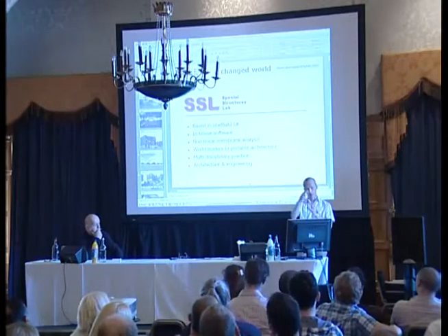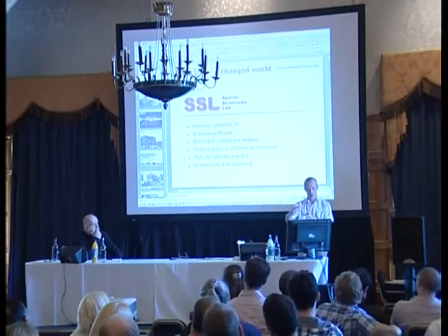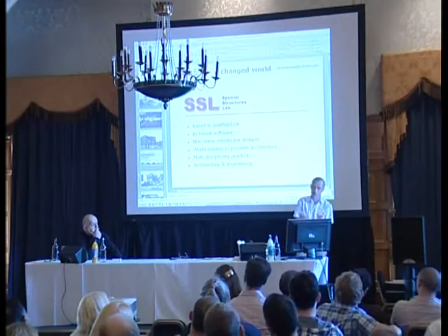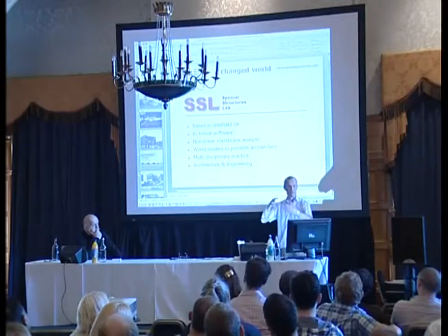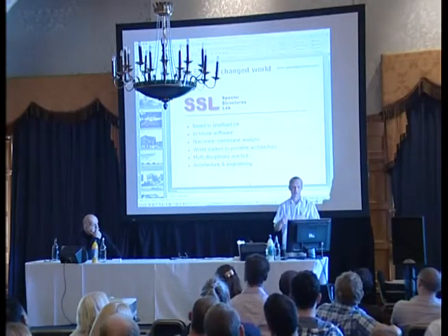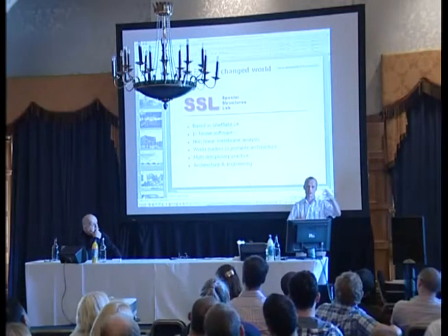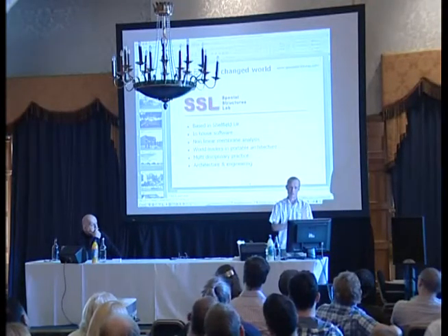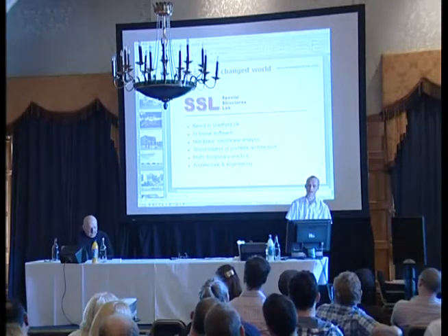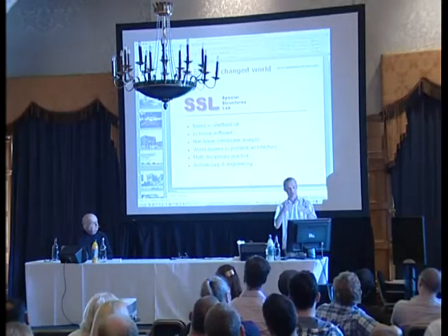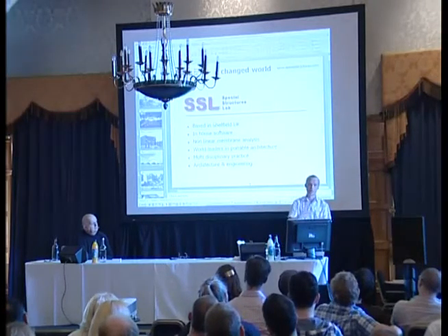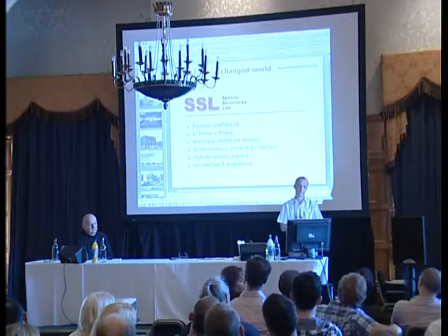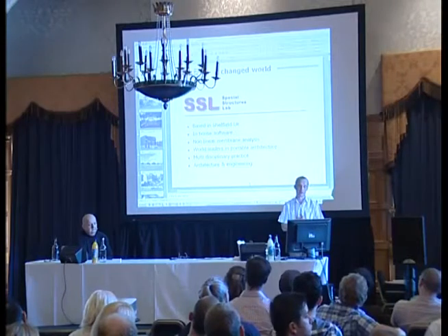And yes, maybe it is, but what I would say is that the supplier should be checking. If you're putting up one of your structures at Glastonbury, you know there's a big enough safety management system that they will be there. But it should be your responsibility to check that the person has the ability, as part of your instructions to them, when you are handing them the wind management plan. Question them beforehand: are you going to have an anemometer? If they ask what that is, alarm bells should start ringing. Or even just tell them their responsibilities: how are you going to monitor what's coming towards you in the next half hour? Yeah, absolutely. Okay, so Brian.